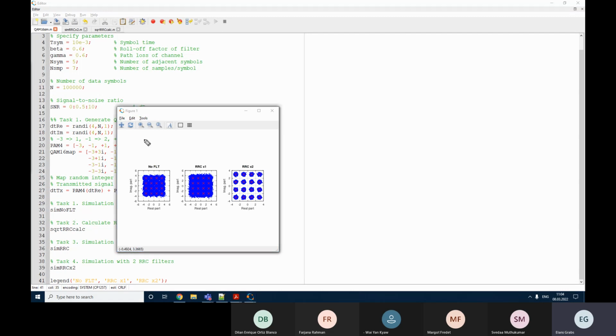Yes, well, this in the middle is actually not what we do in practical tasks. We always do these filters in pairs. So we have transmitter filter, we have receiver filter, and we cannot use any filters. This has to be these raised cosine filters, with specific parameters. Now, depending on your particular system, these parameters can be changed, but the overall idea is still the same.